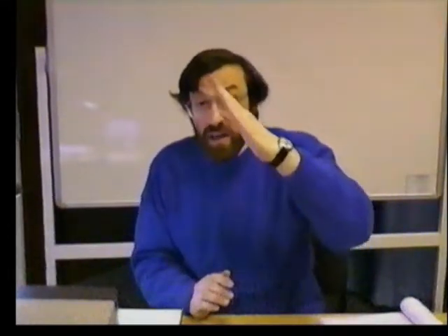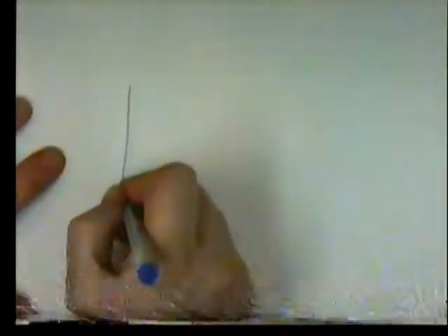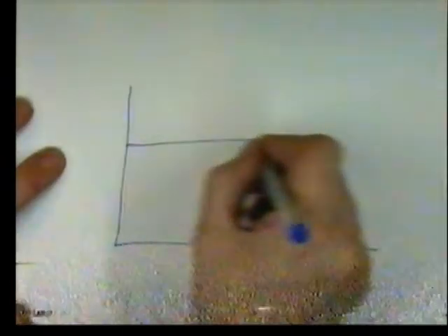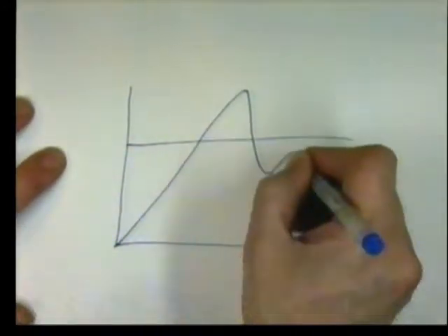When there is a very tiny error, the proportional term is tending to 0, but the integrator will slowly integrate that error, and it will dominate the system, and it yanks us up through the set point. It pulls us through. So we end up with a characteristic response typically like this.